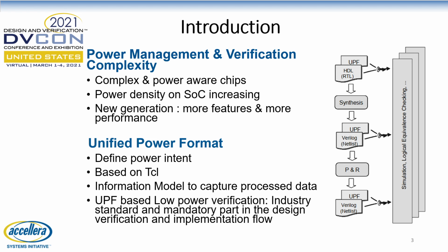So, with this advancement in the technology, low power designs and their verification are becoming more and more complex. Today's chips have multiple power domains, each having multiple operating power modes and dynamically changing voltage levels. UPF based low power verification is therefore now industry standard and a mandatory part in the design verification and implementation flow.